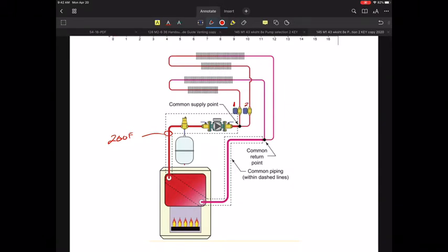In zone valve number 1, we might go through all of those heat emitters in that zone, and in that particular application maybe it comes back at 160 degrees Fahrenheit, which would be, in this case, a 40 degree Fahrenheit delta T in this example.